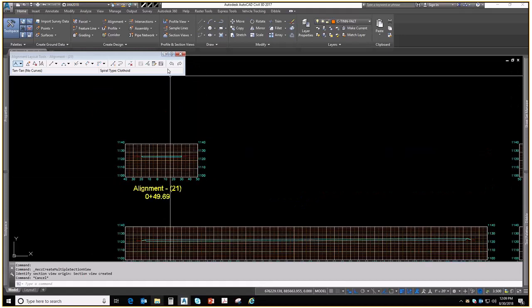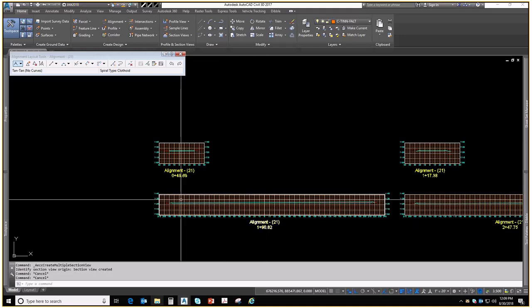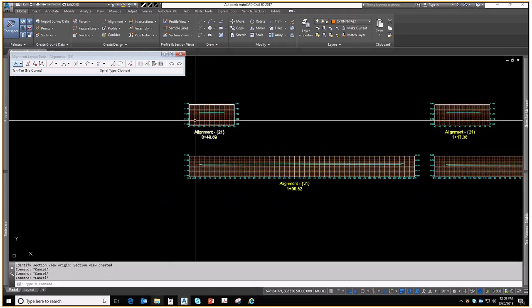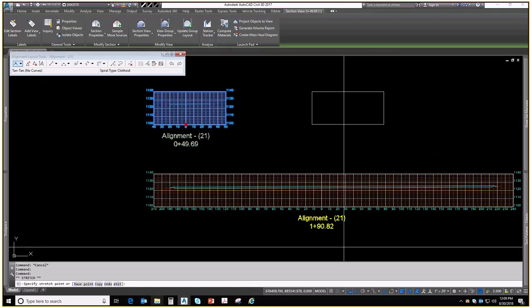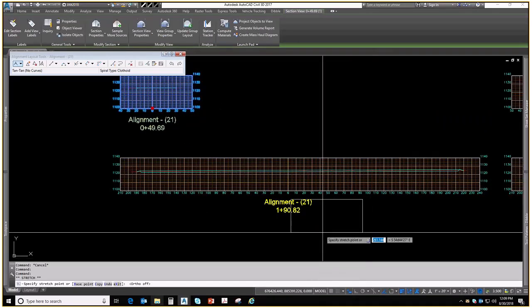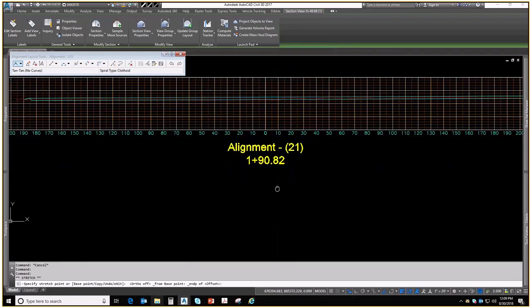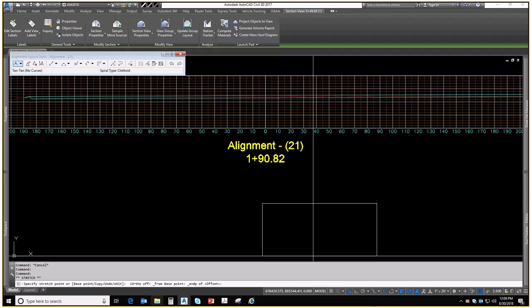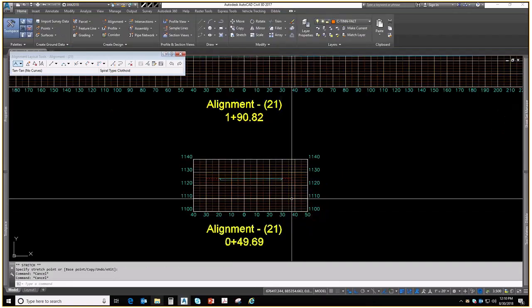Yeah, the standard practice historically has been you start at the bottom and you go up station, so you're kind of as if you're standing on the roadway or taxi or whatever and looking forward, so the higher stations are at the top and the center lines are lined up. So if you're comparing your plan view to your cross sections, you can kind of visualize how these sections march forward along your stationing. So you start low at the stations and move forward.